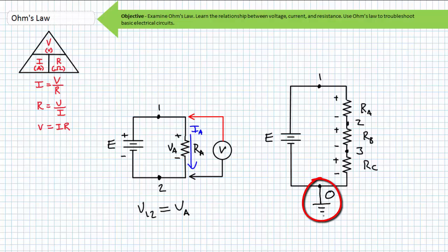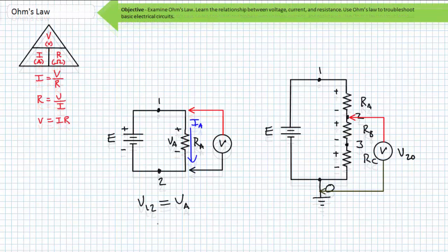Let's say I replaced node 4 with a ground connection and renamed it node 0. I can now use single subscript notation to mean the voltage at specific points with respect to node 0. No sense in saying V20 if you can just say V2, with the understanding that V2 is referenced from this common 0 node. This is kind of just like double subscript notation, where the second number is just not written because they're all referenced from the same node.